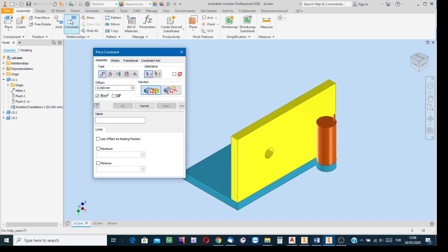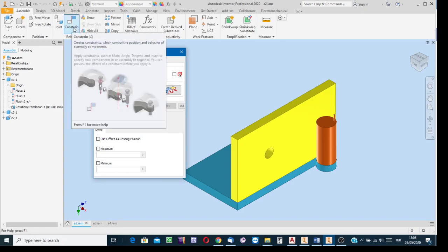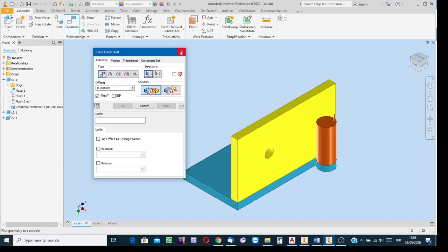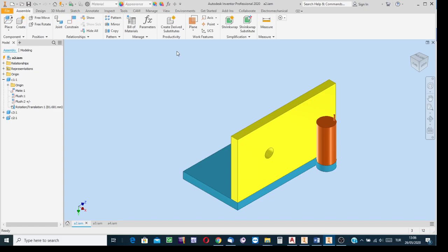You see here, the constraining symbol is on the facility tab, and then we have the icons. Those correspond to the constraints which have been input as the relationship for this with respect to the other. To have a look at which constraints have been assigned for this component, and also to see the offset values or direction options, bring the cursor onto the icon, and when you do this, in the screen you can see a highlighting.